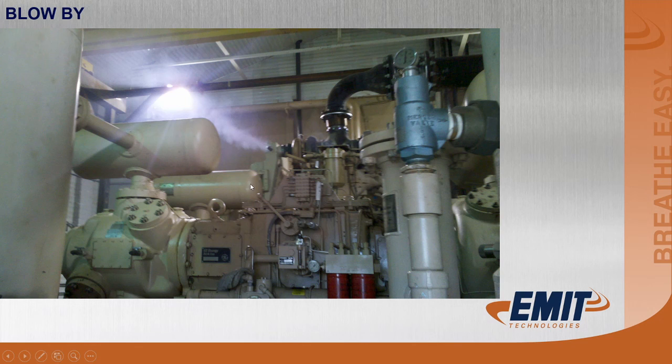Another thing you want to be aware of is certain engines recycle their crankcase gases. On this particular one, the exhaust gases are recycled and put in the air cleaner on this side. This much oil, this much blow-by is very hard on an engine to push back into the engine, and it causes those cylinders to run differently than the cylinders on the other bank.